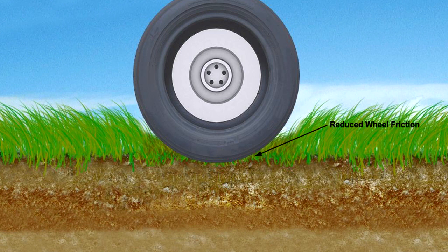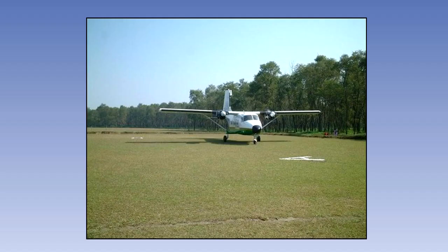Otherwise, the wheel will lock and the wheel friction with the runway will reduce even further. The overall effect is that grass runways will increase the landing distance. In light general aviation aeroplanes, this increase in landing distance is about 15% compared to a landing on a paved surface. However, most landings that you will carry out throughout your professional career will undoubtedly be on hard paved runways.